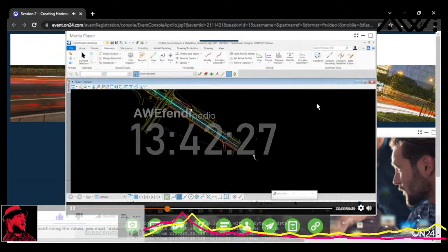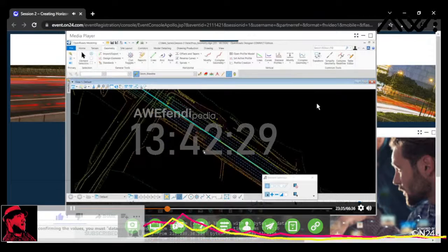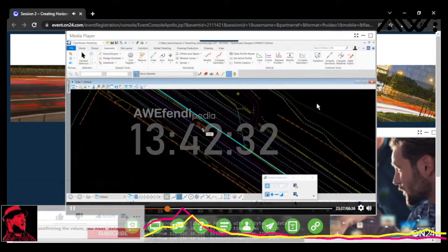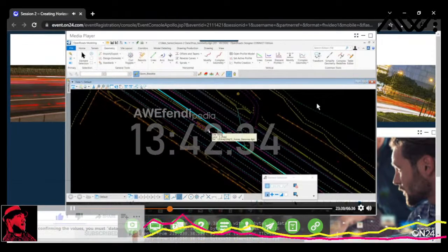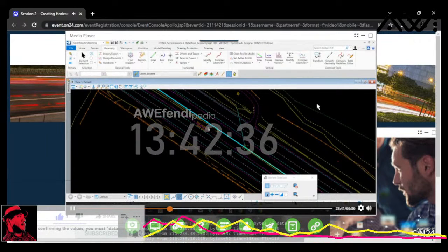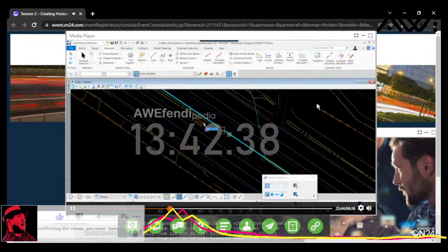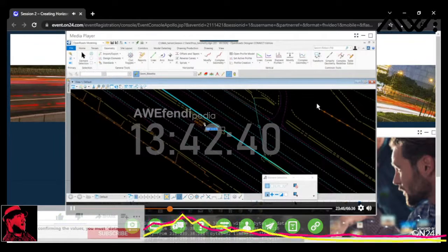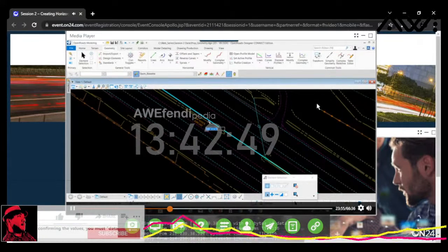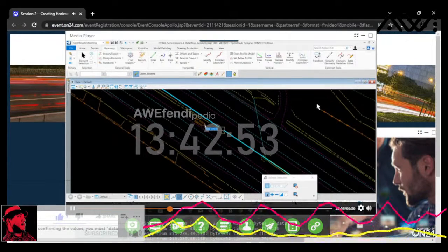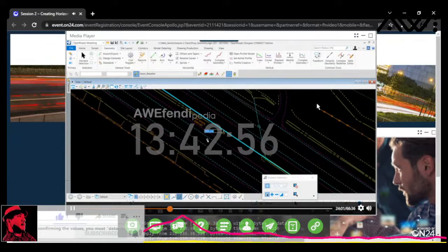Now, I will take a moment here because I want to point this out to you. As you're inputting data, as you're creating geometry, and as you're laying these elements out, it's okay if you happen to make a mistake. You key in the incorrect value for the bearing or the distance or whatever may happen. You can change that very quickly, meaning if you'll notice here, as you select that element, the dimensions, the bearing, the distance are active. I can click on either one of those dimensions directly and make a change. Okay? So it's really no more difficult than that.